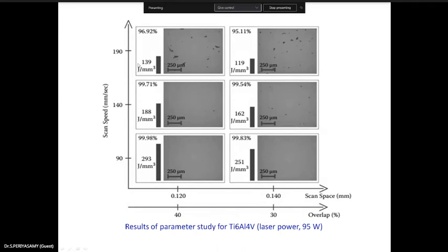The arrangement of this is schematically shown here. Here the light shaded arrow represents the laser radiation that is melting. Then the black shaded one is the melt pool radiation. From that you have images, interpreted to tell whether the entire pool is melted uniformly and solidified or not. So here you have a working plane. From the working plane you have a scanner with a focusing length.